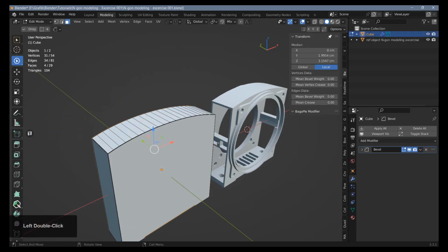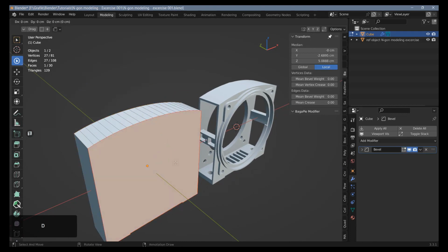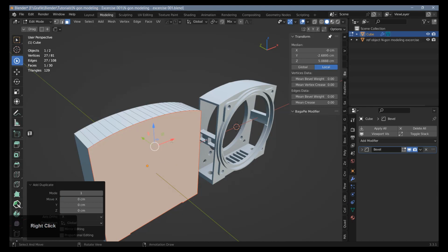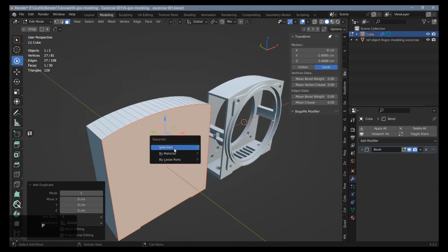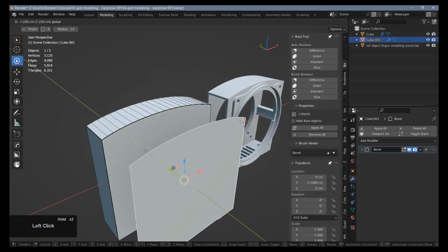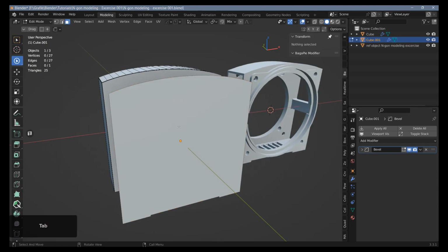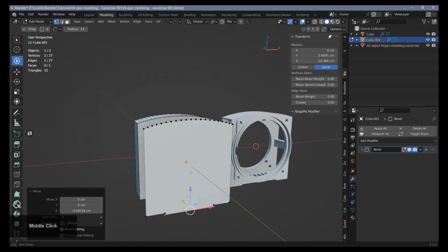In order to create the cutout, we can use the geometry that we already have. I'm going to select the face here at the front, hit Shift and D to duplicate it, right click to keep it in its position, and then hit the P key and split the selection off. Let's select our new object here and move it forward a bit, and here I'm going to move these two vertices down a bit, and this will be my inset.